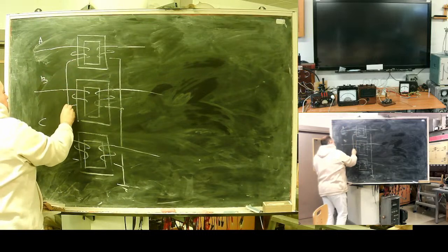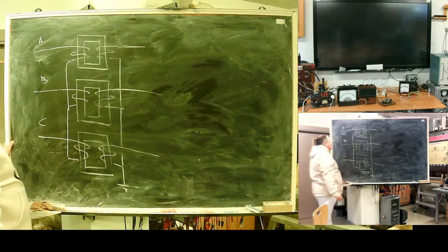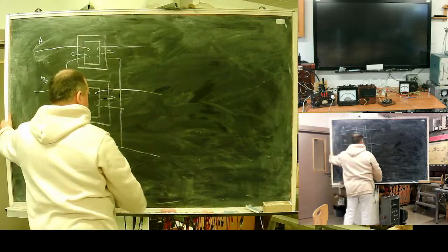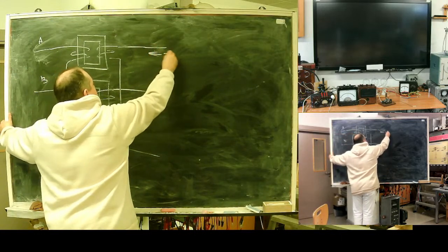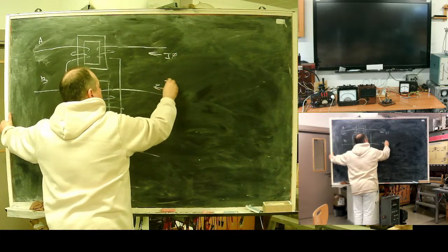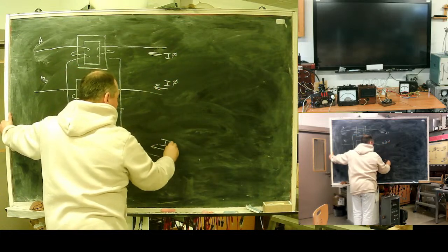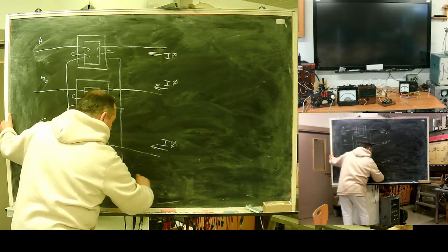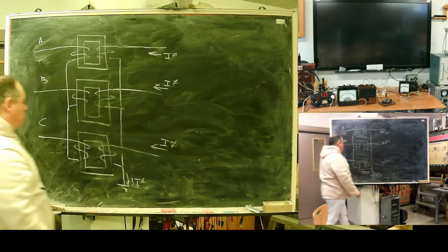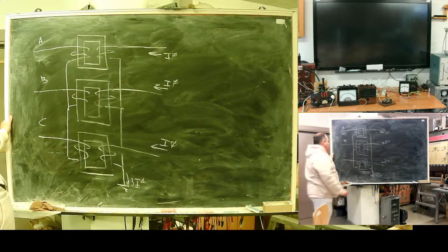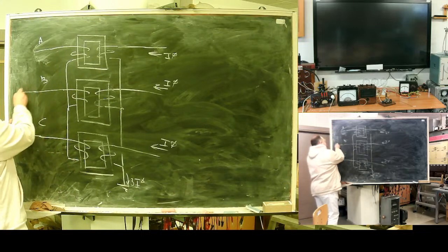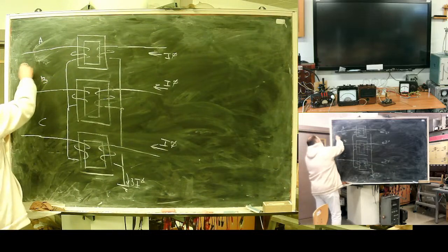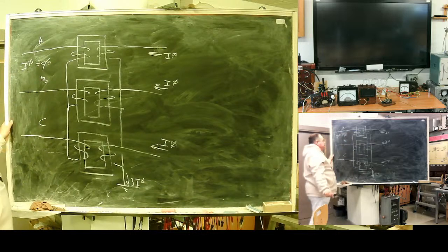And one of the possible things: the network on the side is an isolated neutral network. So we will have zero sequence current. Here triple zero sequence current should be drawn. But since the neutral on the left side is isolated, it is 0, and here is 0.